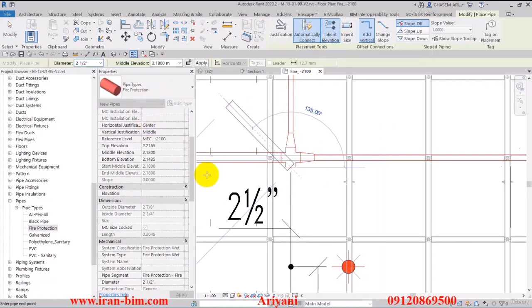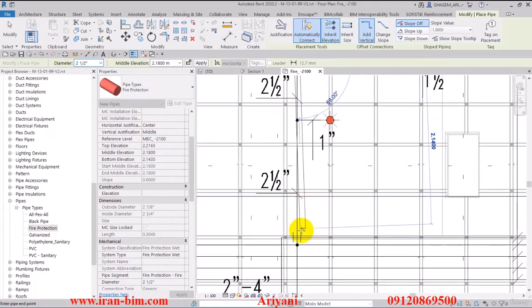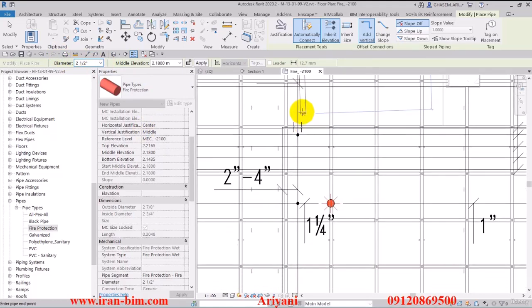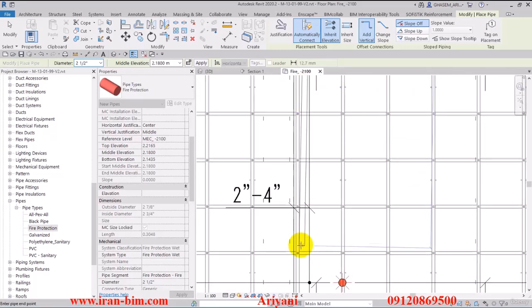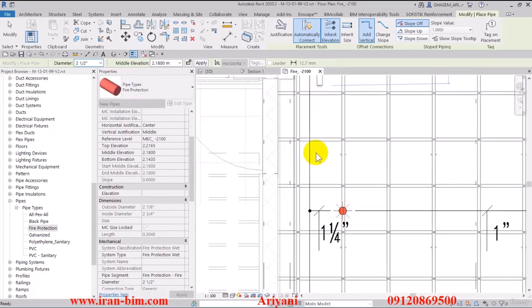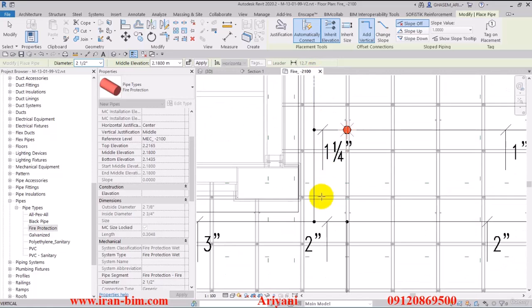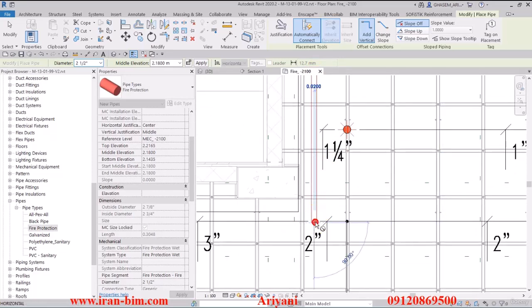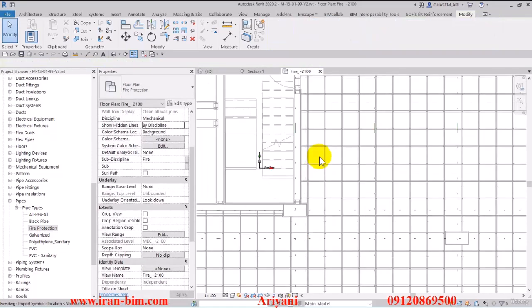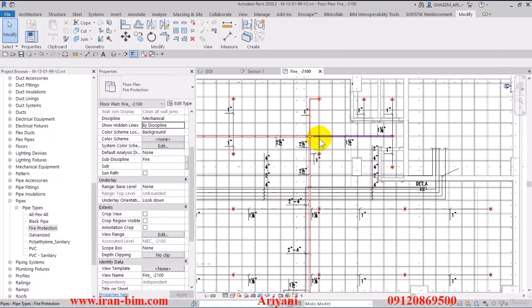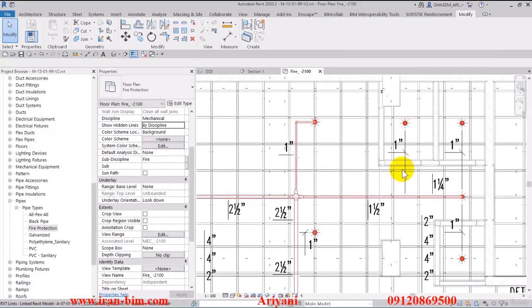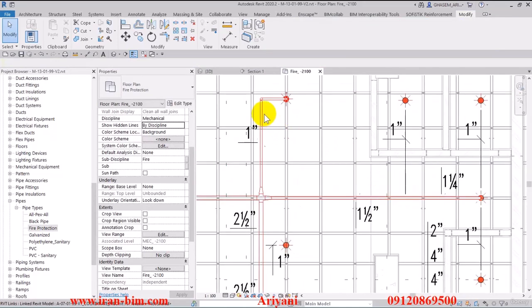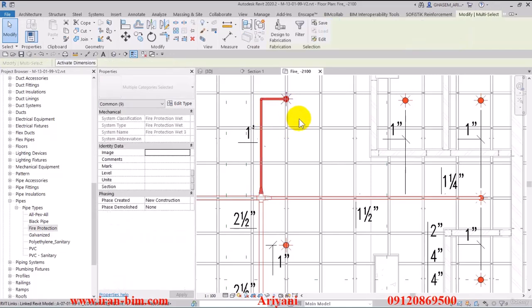I'll match the height using the inherit elevation option up here, and here we can see the diameter set on 2.5 as well. Then drawing the pipe, we go down here through the plan all the way through these structures, passing these and then finishing for now at this point. Then later on we can divide it. All of the pathways are done in the same exact way.